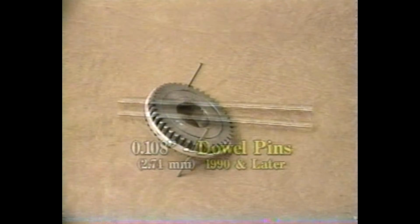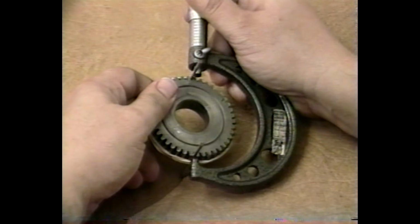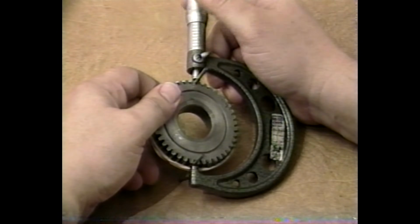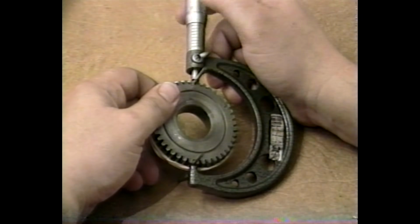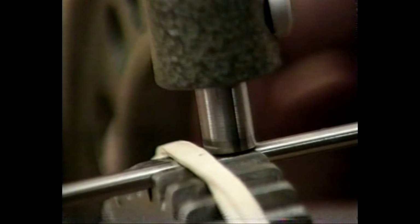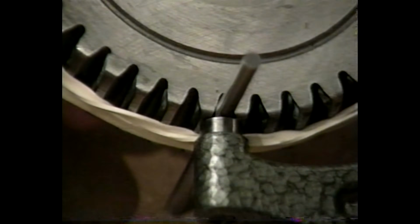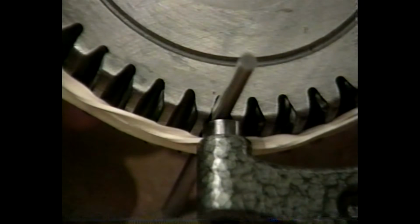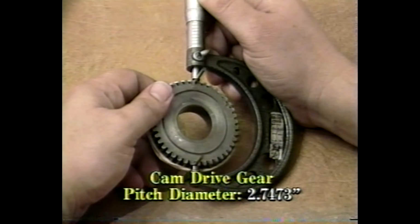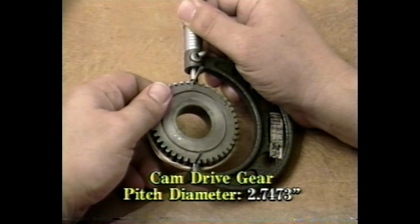To select the matching pinion gear for our Crane Cam's camshaft, we must use 2 dowel pins that are 105 thousandths in diameter and mic the pitch diameter of our camshaft drive gear. We place 1 dowel pin firmly between the teeth on one side of the cam's drive gear diameter, and the other dowel pin is placed firmly between the teeth on the opposite side of the drive gear diameter. Holding both dowel pins firmly in place with a rubber band, we use a 2 to 3 inch outside micrometer to measure the pitch diameter of our drive gear, which in our case is 2.7473 inches.